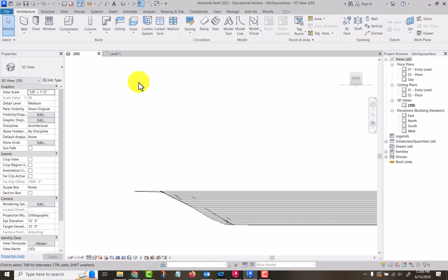Okay, this week we are going to be working on site tools. Revit can develop a site plan, a topo surface, if you will. It's not a replacement for Civil 3D or the drawings from a civil engineer, but it will give the architect the ability to create a 3D surface and do some estimated grading, if you will. See how the building sits within the ground, and then you can add